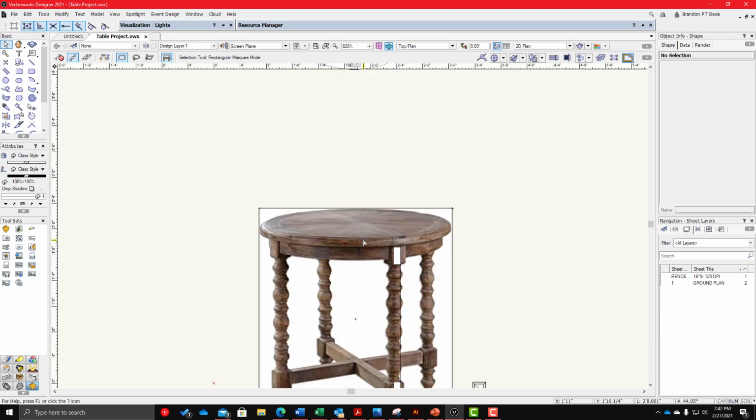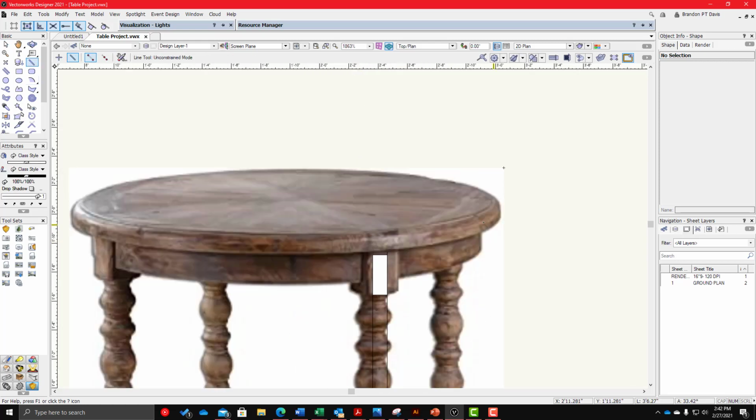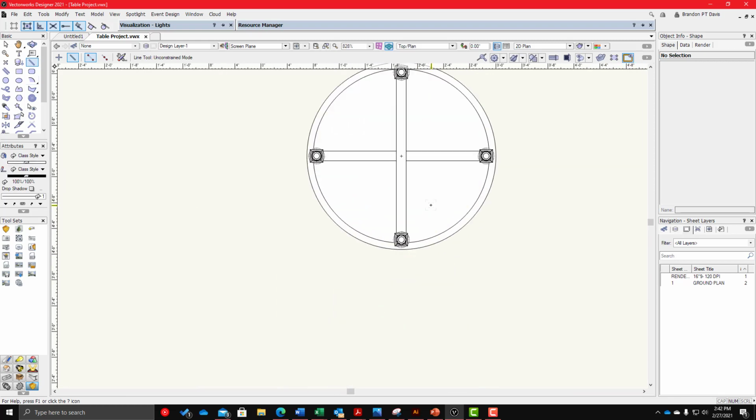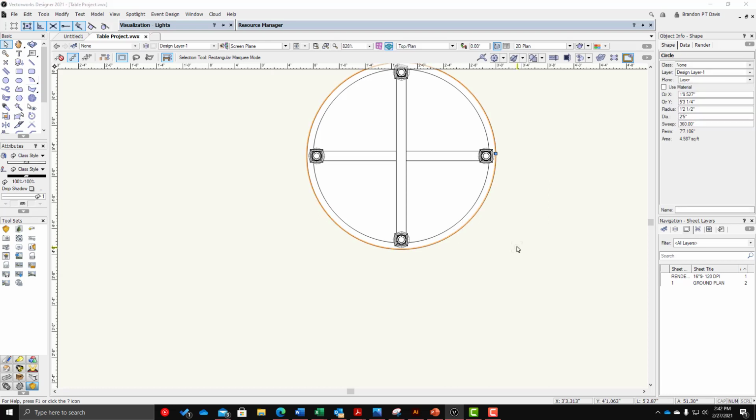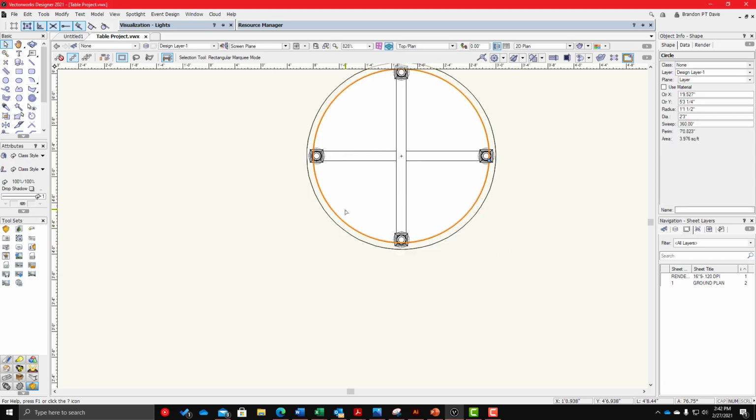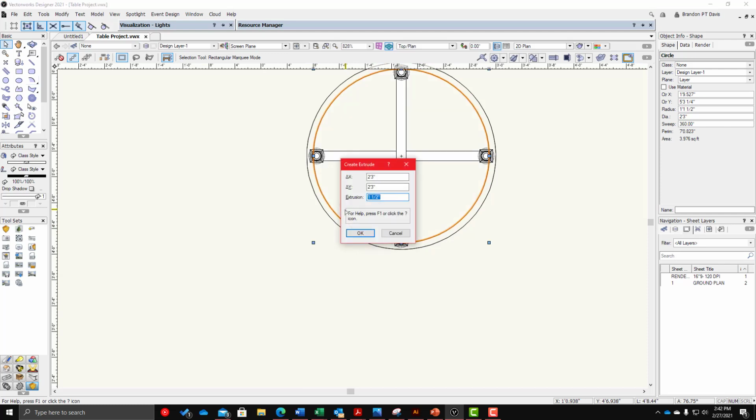Now the next thing we need to do is get the height. So the estimated height of this is about 1.5 inches. That's pretty proud. And then this is about another 1.5 inches. So I think we're going to go with 1.5 inches on both of these extrudes. So I'm going to hit Command E. I'm going to make this 1.5, and then one on the bottom, Command E.